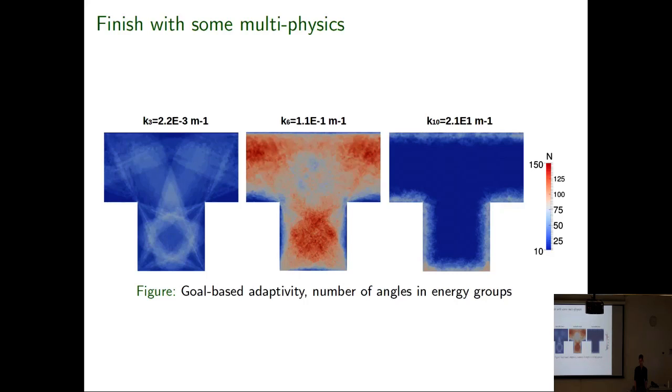Yeah, so we've got a weird spatial discretization. It's a CG plus a DG, essentially, where we do a static condensation on the DG bits. And it's Schur complemented together, and we use an approximation for our DG part to make it scalable, because it's bigger and more coupled than the CG version, essentially. So those DG bits also get projected down onto the lower grids as well. So what you get is essentially combined stabilization from all of the elements that you've glued together.